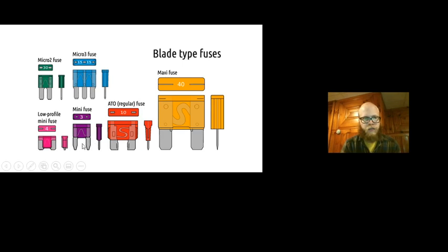In a pinch, one of these mini fuses will plug in and work, but usually the cover for the fuse panel won't close anymore, so you can use it for testing. And let's say something comes in with a popped fuse because the switch shorted to ground, if we were trying to diagnose that, it might be nice to be able to pop a fuse in that we are likely to have handy. If we need to order some fuses from Napa, or if the parts department's all out and they have to order it from a warehouse or a distribution center, at least that way we can keep on trucking with our diag and keep getting some stuff done.